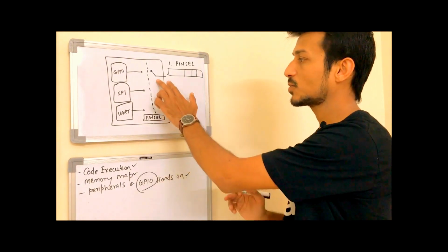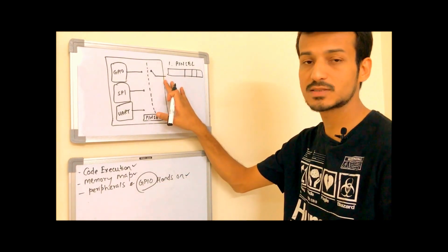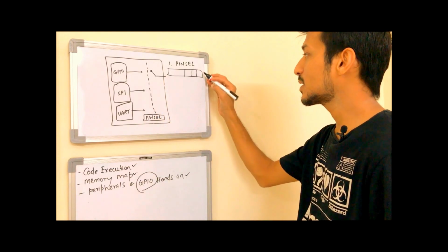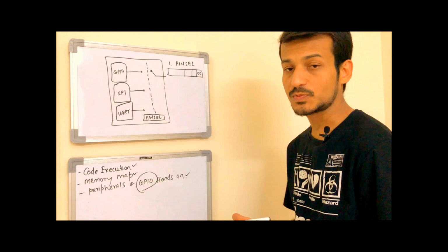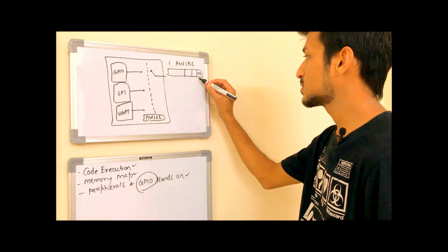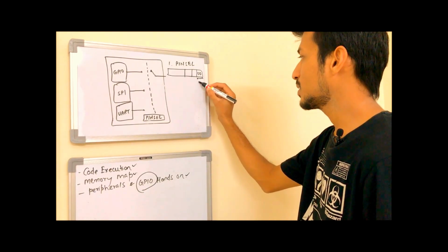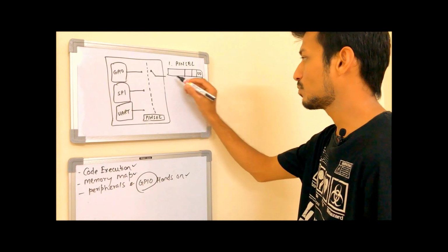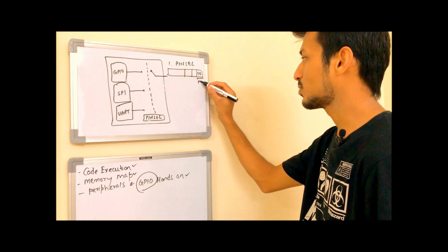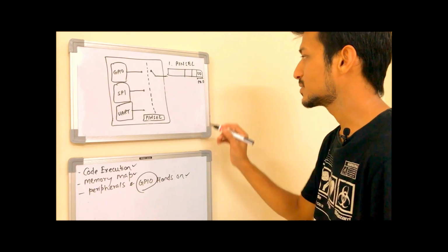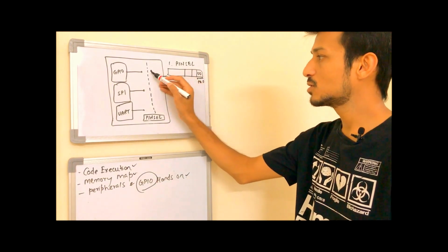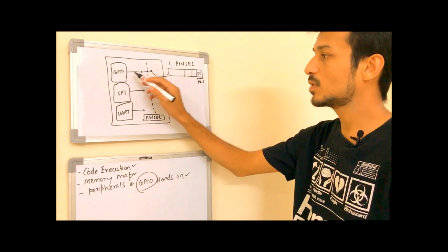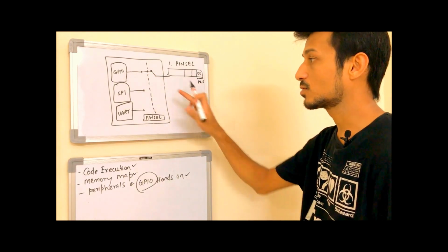Because there is a possibility of 4 peripherals at one pin, the pin select register associates 2 bits with each pin. So let's say for the pin number, we assume this is port A0. Port A0 has 2 bits. If these 2 bits are 0 0, this pin is going to be a GPIO.